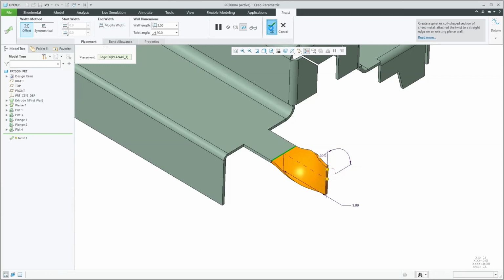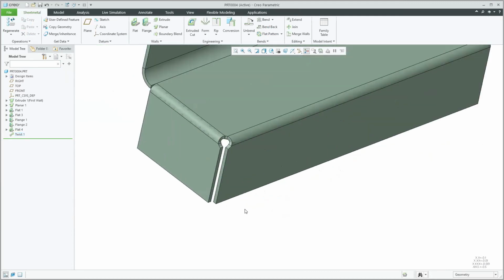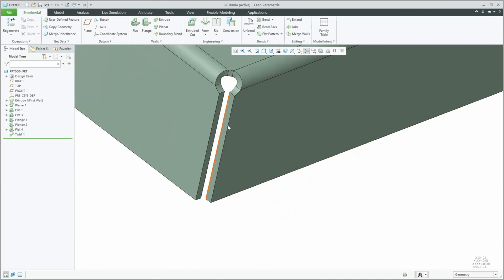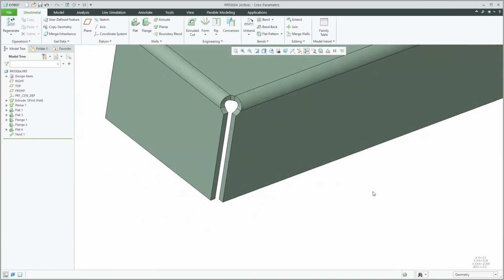And then the extend. What if I need to go through and make a wall a little bit longer? Okay, I got left this gap here and I want to extend this out. I could go back, of course, and edit definition and change some settings, probably solve that problem. But a little bit faster maybe is just to come over here and extend it.